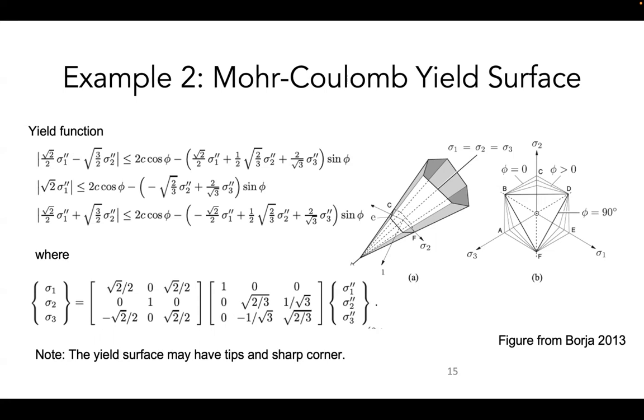So the idea is the following. The actual yield surface on the pi plane could look something like this. It has those regions as well, where it goes to infinity, but I'm just taking that they have to be included in all the criteria. You can easily see that if it's not smooth, it becomes much harder to detect whether I'm inside or outside, because I have to check all of them one by one. You see what I mean?